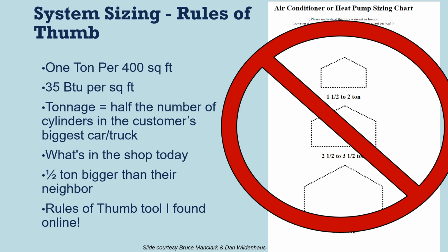So we try to avoid as much of this stuff as possible, and instead lean into things that, again, if we want reasonable results, we have to take into account where the place is. So I mentioned earlier, Minneapolis, Minnesota is going to be very different from Seattle, Washington, which is going to be different from Fort Collins, Colorado, which will be different from Nashville, Tennessee. So where it's at, how big the house is, that's going to matter, right? A 3,000 square foot house and a 1,500 square foot house will simply need different amounts of heat. And then how well air sealed and insulated is it, and where is the ductwork? If it's all ductwork in the basement and it's a fairly well insulated home, that's going to be very different than a 1910 really old house with very little insulation. It's very leaky, right? So each of those things need to be accounted for in some way, shape, or form.